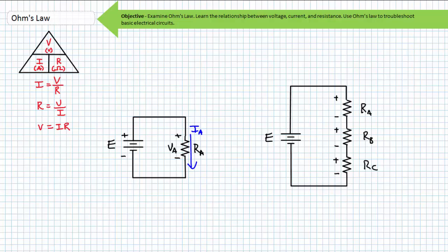This level of detail breaks down if you've got nodes in there using the same identification scheme as your components. So we've got to establish some ground rules. Rule number 1, use different identification schemes for components and nodes. If components are letters, nodes are numbers, or vice versa. Rule number 2, voltage is a two-point measurement. If resistor A is hooked between node 1 and 2, I can say that the voltage drop across it is VA, or voltage at node 1 with respect to 2, or V12. In this case, V12 is equal to VA.